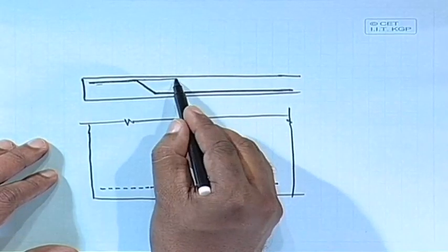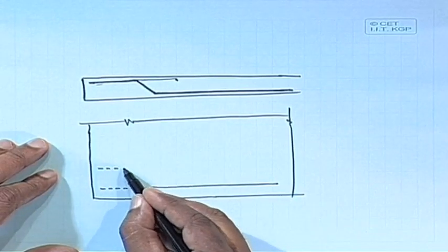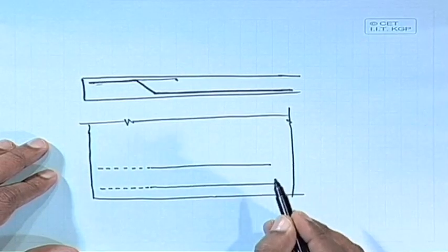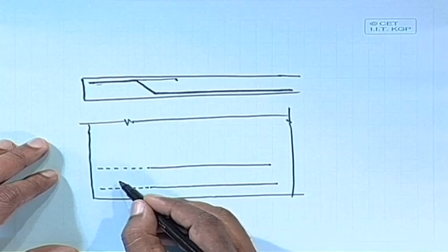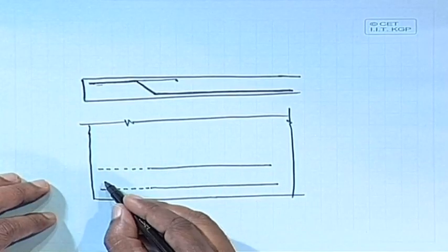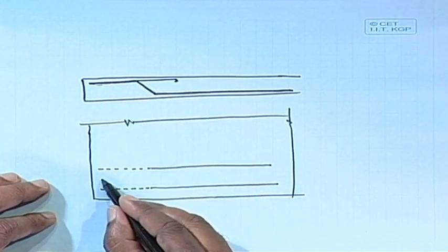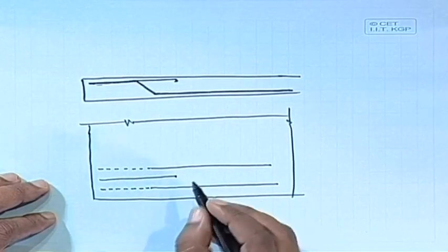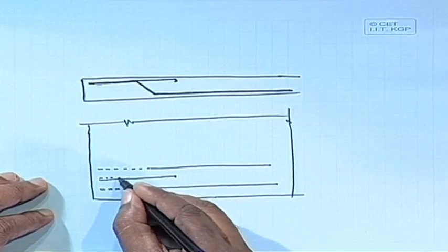The other one, because it may not be sufficient. So, we can specify the other bar like this, it can go and then again firm like that, but in between the spacing is not sufficient. Let us say this spacing is not sufficient, we have to specify a little more bars. In that case, this is another bar, this is another bar, and we specify another bar like this. This cut piece we specify here like this, so that actually it should be dotted. Please excuse me, it should be dotted.